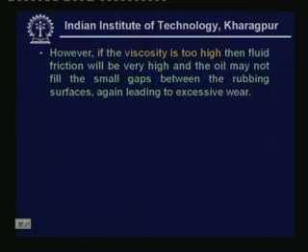So when the viscosity is very low, it will not act as a good sealant, that means the gaps will not be filled with the oil, so there could be leakages, right. And what happens when the viscosity is very high? When the viscosity is very high, the gaps may not be filled with the oil, because the oil may not flow into the gaps, especially when the gaps are very small.